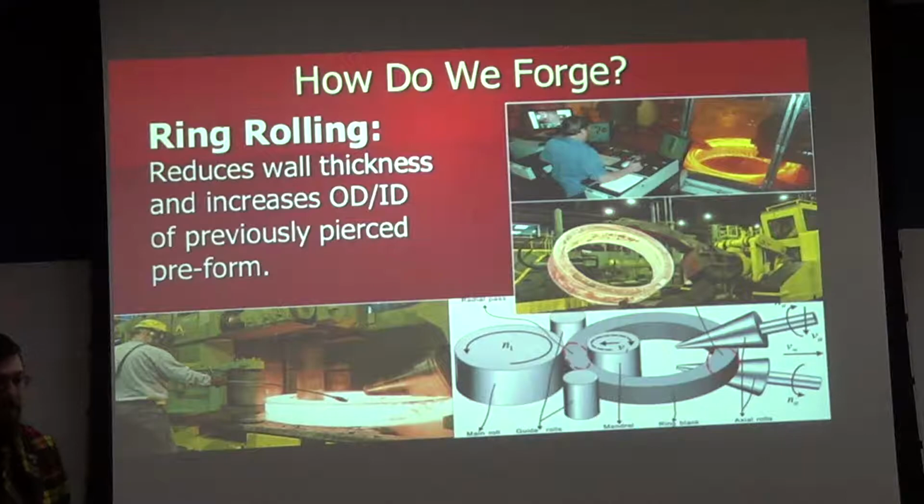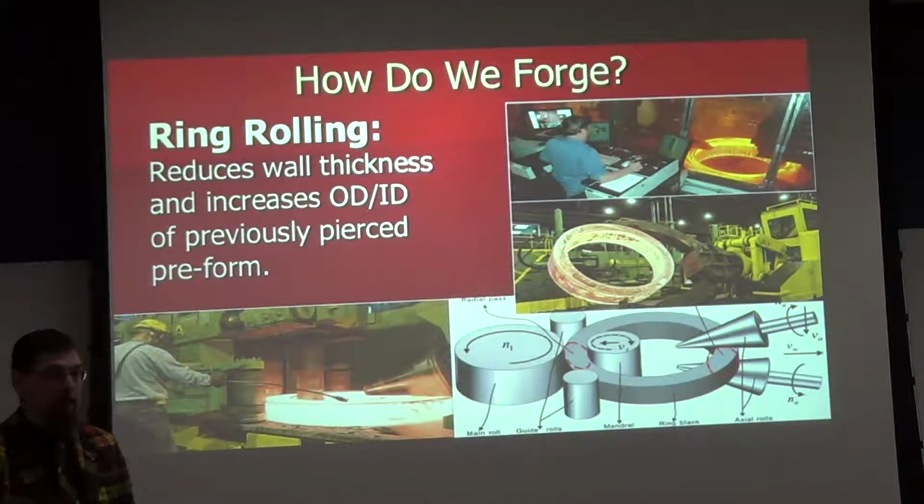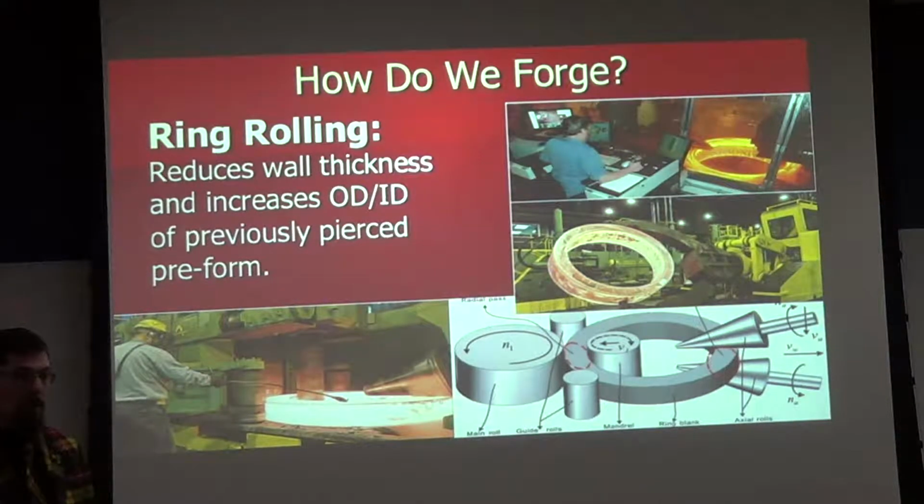Welding does all sorts of weird stuff in microstructure, so it'll definitely be more uniform when you don't want a single hard spot or soft spot in the piece. Good, yeah. When you weld something, you make a sort of interface. Whereas if you just forge it, you don't have an interface to deal with. It's just one continuous piece.